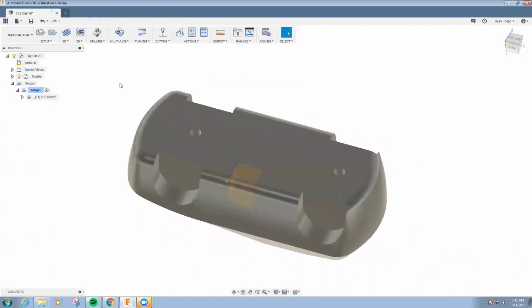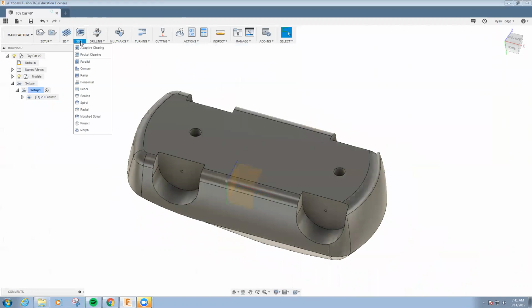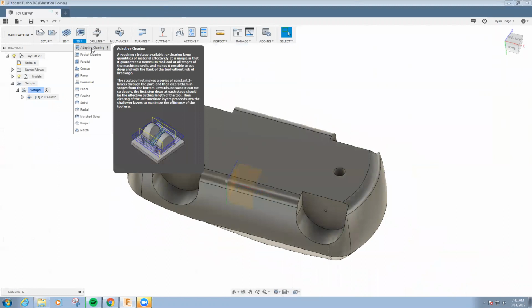That looks pretty good. The next thing we're going to do is mill this perimeter pocket here. So to do that, I will use the 3D dropdown. And there's a bunch of different options, but the two best options are the adaptive cleaning, which will remove all material on the plane that we mill down to. And if we were making this out of, say, aluminum or even wood, we would want to definitely use this adaptive cleaning. It removes material that the machine could potentially run into later.